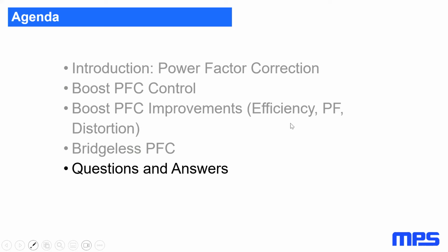No, I don't think this is true. I think even at 100 kilohertz, you will benefit from using GaN. You will potentially have less switching losses, and no, I don't think this is right. I think you can get some improvement by using GaN even at 100 kilohertz.